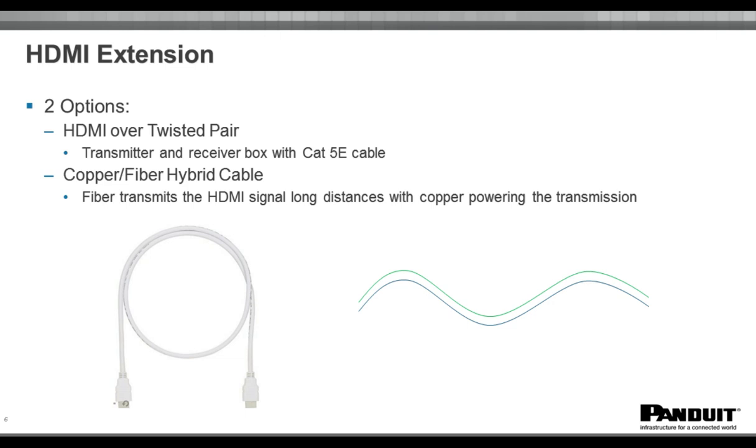This is going to be really important because you want your customer to get the full investment of their AV system. You want them to be able to transmit that 4K video. And oftentimes with a lot of patch cords on the market right now, if they're not certified premium 2.0, they often aren't going to pass that 4K video signal. And you're going to run into a lot of problems when you start looking at HD-base-T systems. It's actually going to affect some of your handshake and EDID, or extended display identification data, by using a low quality patch cord.